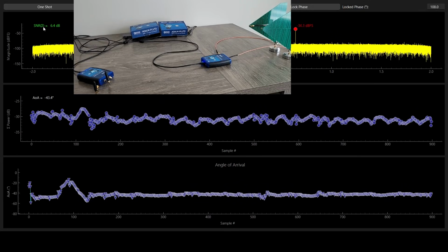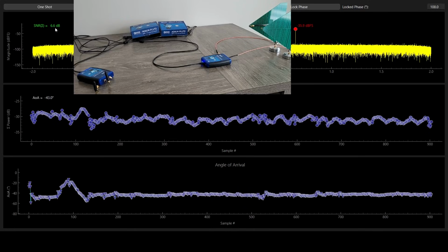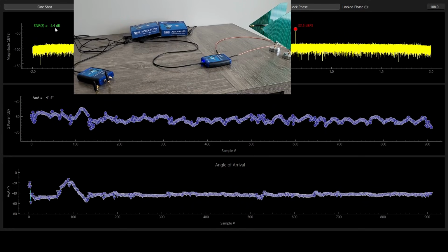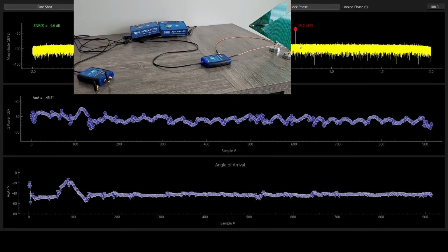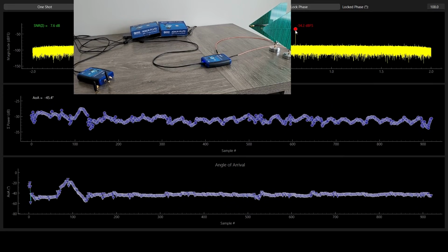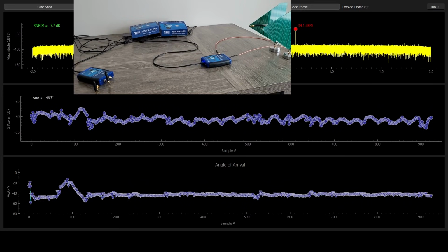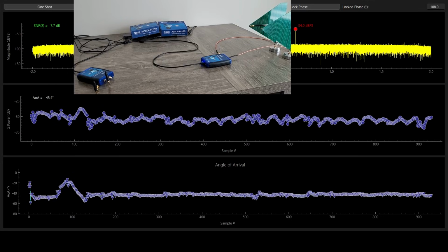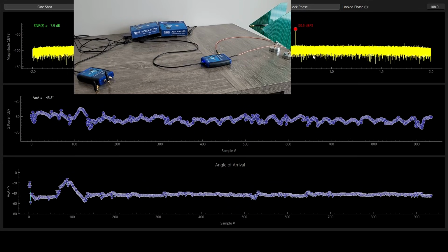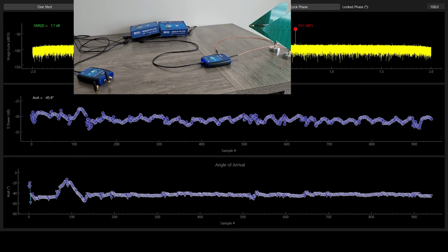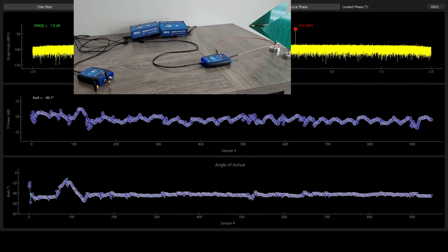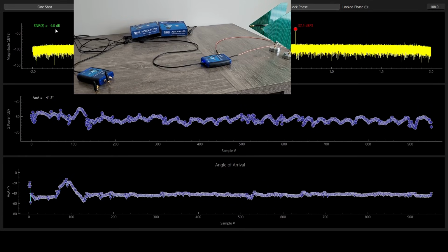For this SNR, this is not a very robust definition of SNR that I'm using here. Basically, what I'm doing is that I'm picking the amplitude of the main tone and then integrating the amplitude in the other regions, which can be a very wide region, and find the ratio of those to measure the SNR.